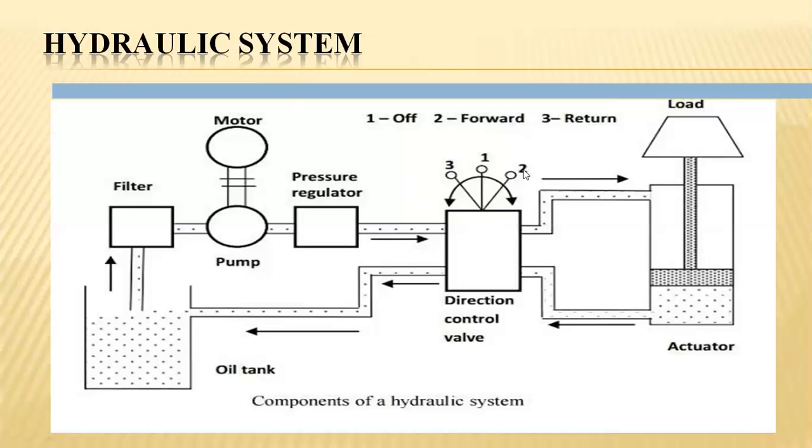If the second position comes into existence, then the fluid enters similarly, and here the position will be in a cross linkage. So the entering fluid comes in this direction and the leaving fluid comes in this direction through these hose pipes. Hence, the fluid enters from the cross terminal, in the opposite direction to the arrow mark specified in the diagram.